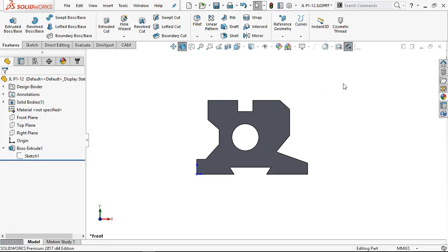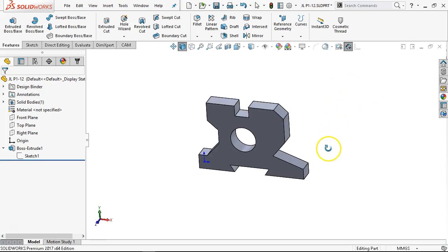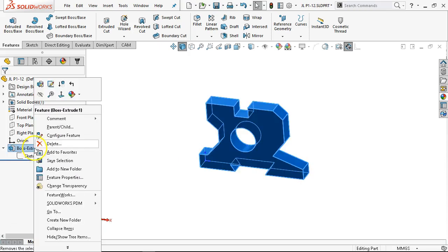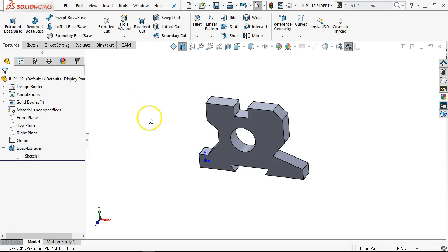But you need to be aware of those other selections. You know, if you hit something accidentally on the keyboard, what did it do? All right, so getting back into the sketches, getting back into the features, everything's going to be pretty much on the right mouse button and waiting for the tooltip to come up, edit feature, edit sketch. Those are going to give you kind of the clue of where to go.